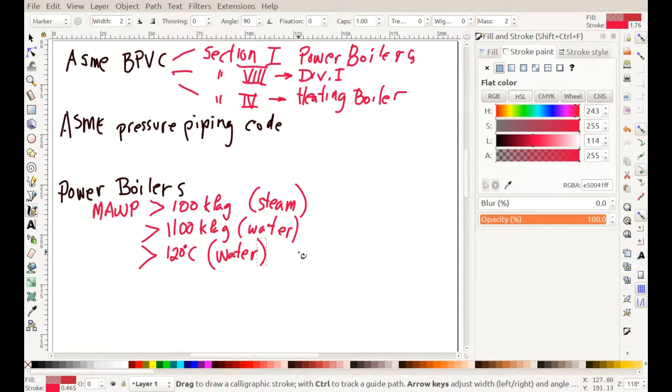And where that exists, they often say, well, the Power Engineers Act or the Power Engineers Regulations, whatever, it kicks in. So you can have a first-class hot water plant. And I'll give you two examples. In Manitoba, the nuclear research facility in Pinawa, Manitoba, was a first-class plant. They didn't make steam. They had high pressure, high temperature, hot water. And another place that I inspected was the North End Water Sewage Treatment Plant in Winnipeg, which was a first-class plant because of its high pressure, high temperature, hot water. And all their boilers were power boilers.